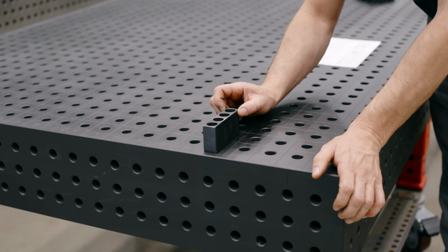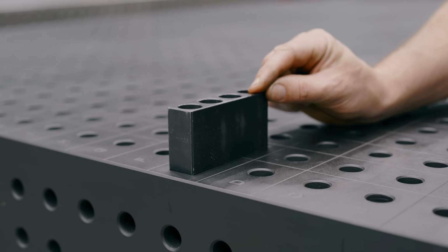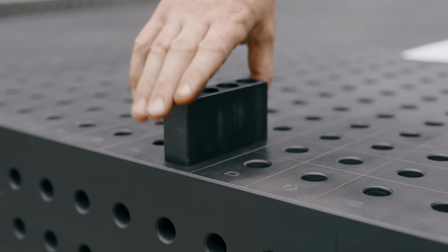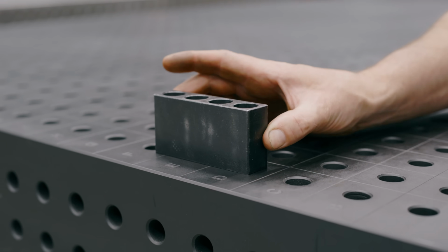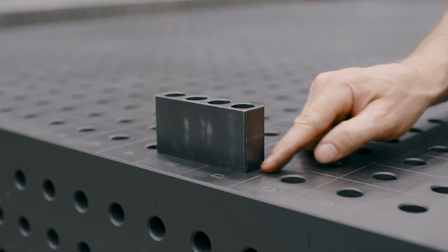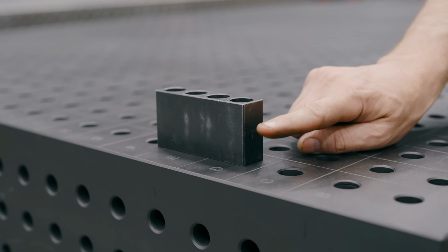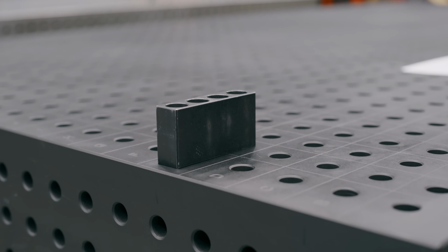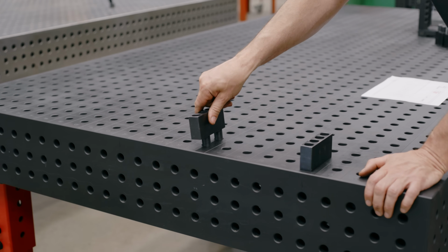Now remember earlier in this video I told you that they had a little bit of wiggle. What I mean is, if you're going to fixture up against the side, see that little bit of wiggle right there? That might throw you off, it might not. But if we were to turn it this way, you see how it doesn't have any wiggle? This is why I like building off of the ends, because it's a 90-degree angle and the side movement doesn't affect this reference surface right there. So that's why I like to turn them just like that. All right, so all I've got to do is follow the holes and we'll whiz bang through this really quickly.